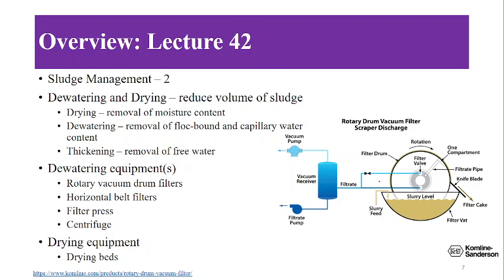And you might have heard one more term, which is thickening. How is it different from dewatering or drying? Thickening is the removal of free water which is there. And drying and dewatering are related to the removal of bound water which is present in the sludge.